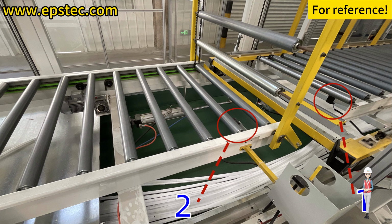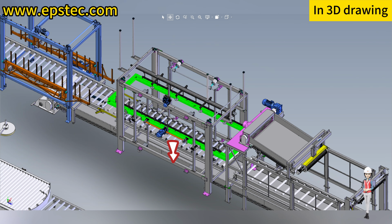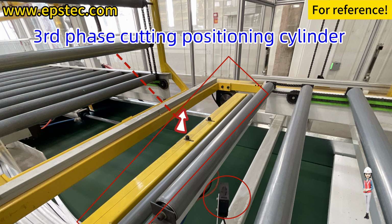When the cut EPS boards completely leave the first and second photoelectric sensors, the bridge connection cylinder extends, and the connection frame is in an upright position. The cross-cutting frame returns to the lower limited position, and the position cylinder extends, waiting for the next EPS block.